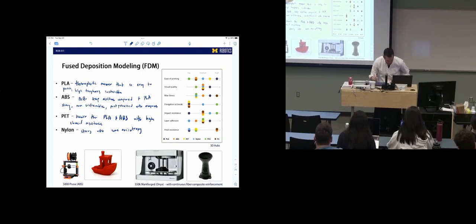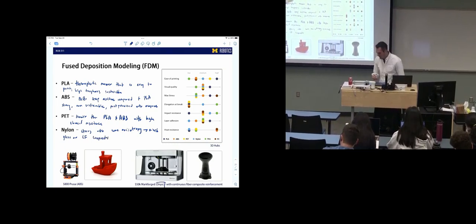So it has semi-anisotropy. This is mixed with glass or carbon fiber composites. This Onyx that we're seeing right here, Markforged Onyx, that's their name for their nylon material. So some of these 3D printer manufacturers have a material that they call their material. So Onyx is what Markforged calls their nylon. Or it's a nylon-like chemical, and that's what's laid down with the filament.